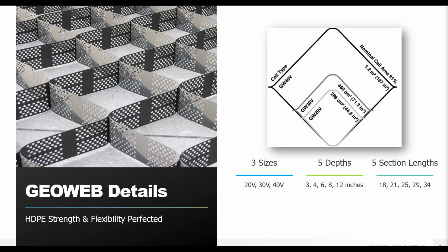So something else I want to point out is the ultrasonically welded seam. That's where all of the connecting points are, and it's very important to the function of a GeoCell. The stronger the seam strength, the better the performance that the GeoCell will have. A strong seam allows for heavier infill materials, steeper slopes if you are on one, and better overall lifetime performance.